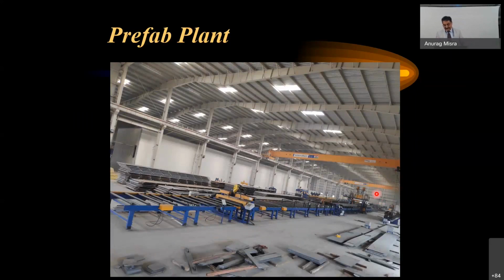It starts from that side where the plasma cutting machine is there. Cutting is done, and then these plates, different components are stacked. Then you take it there, and the one machine, maybe in 15 to 20 minutes time, your 10-meter girder, because if you are going for, let's say, a 30-meter girder, you have to make it in three pieces. Otherwise, the transportation won't be possible. So that is how we control, and it actually goes through it.